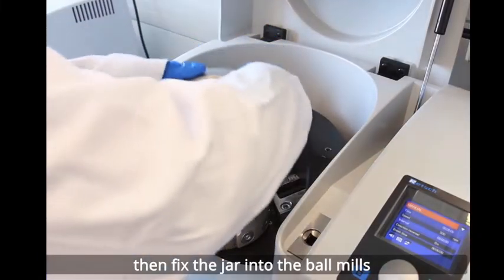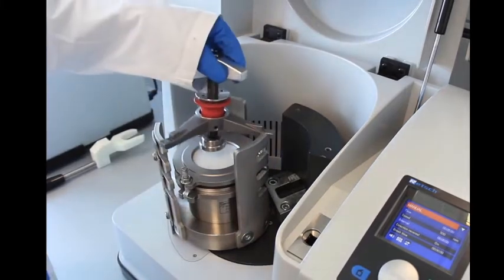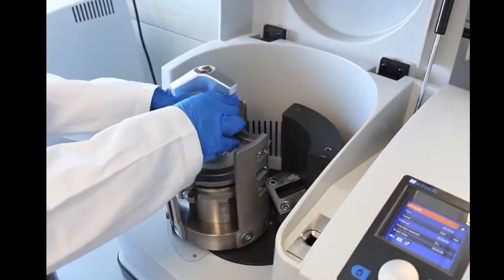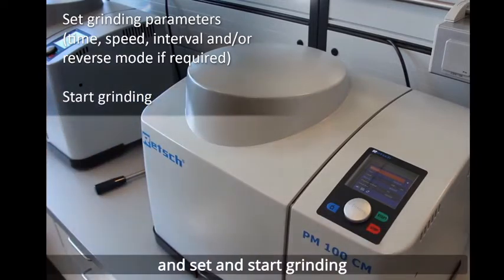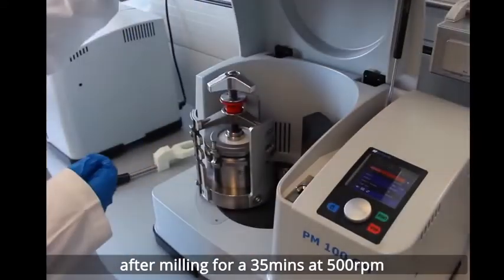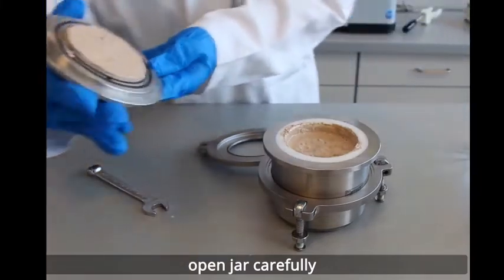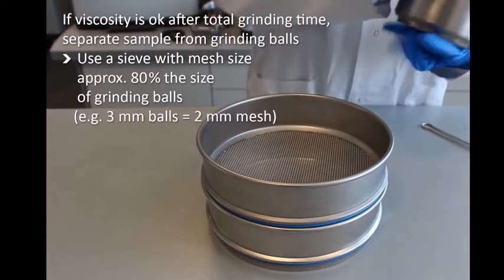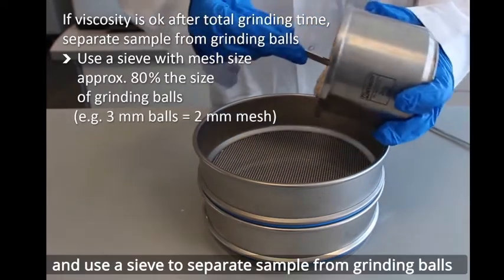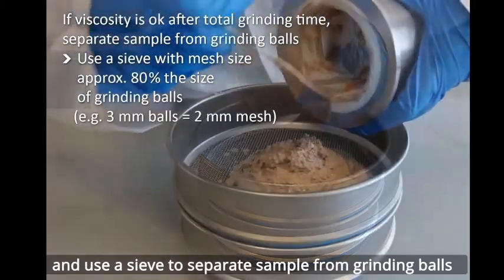Then fix the jar into the ball mill. Start grinding. After milling for 35 minutes at 500 rpm, open the jar carefully, and use a sieve to separate the sample from the grinding balls.